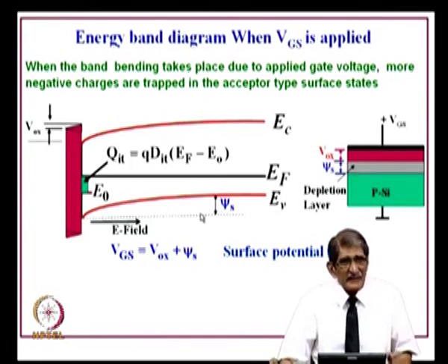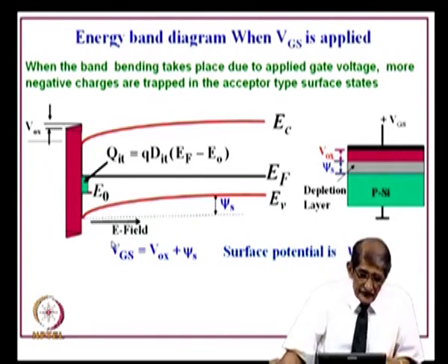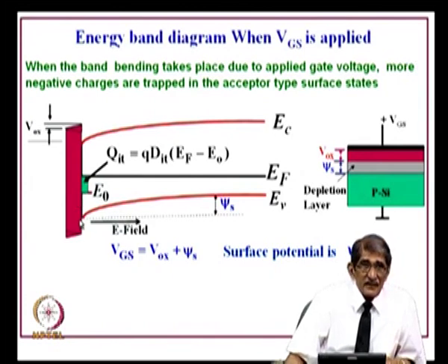When you say depleted, a very casual way of telling is it is less p type, because the depletion is not abrupt, it becomes less and less holes are present, very few holes are present here. So, less p type. So, the distance between the Fermi level and the valence band increases, but the neutral level location is always fixed with respect to the valence band edge. For silicon, this is Eg by 3.